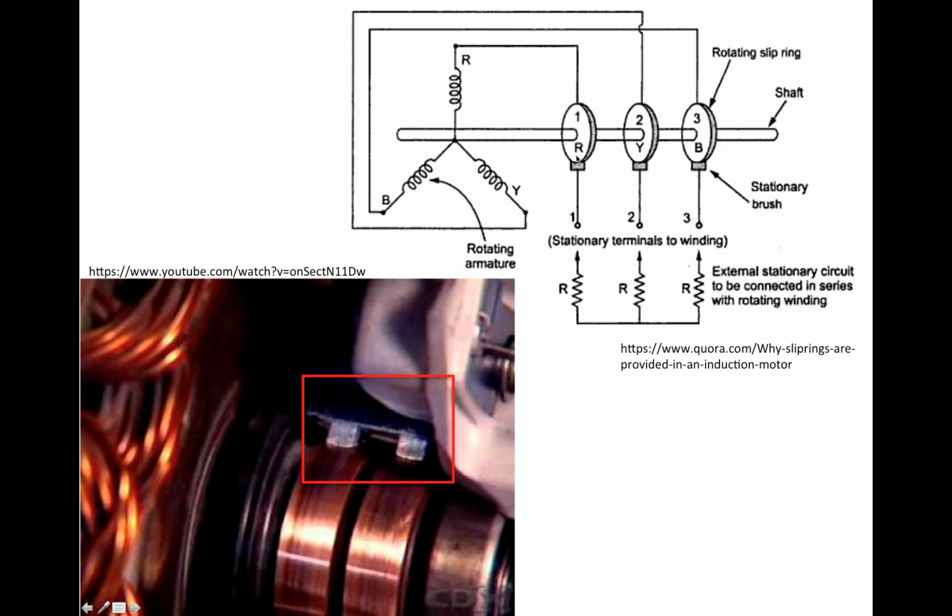That metal collar connects those slip rings together, and the brushes can be automatically lifted from the slip rings to avoid any friction, wear, and tear. If you lift the brushes, they lose contact with the slip rings.